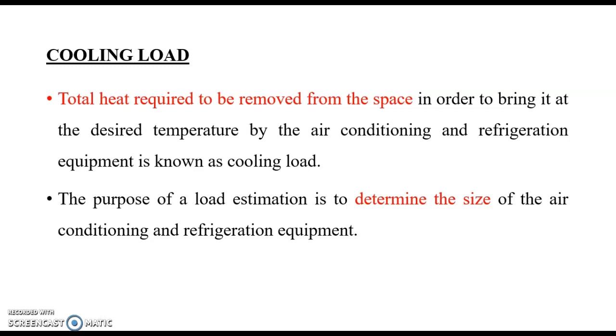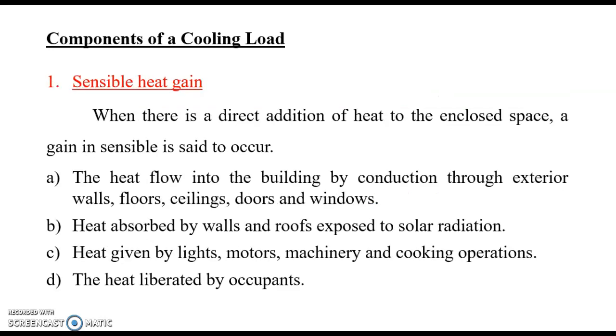Cooling load. So we are going to define what is cooling load. The total heat required to be removed from the space in order to bring it to the desired temperature by the air conditioning and refrigeration equipment is known as cooling load. The purpose of a cooling load estimation is to determine the size of the air conditioning and refrigeration equipment to maintain the desired temperature of the confined space.